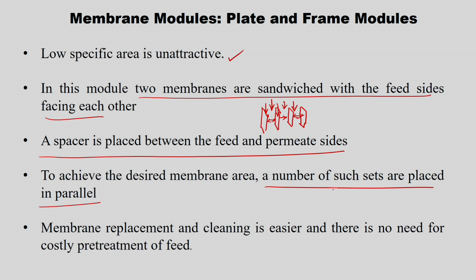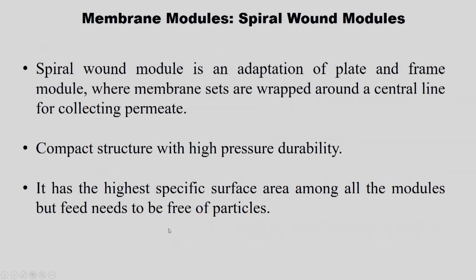So, based on the desired membrane area, these kinds of modules can be connected together to achieve a particular desired membrane area. The membrane replacement and cleaning is easier because it comes with separate modules. So, you can assemble and disassemble them based on your requirement, and cleaning is easy, it can be disassembled very easily, and no need for costly pretreatment of the feed, that is also an advantage.